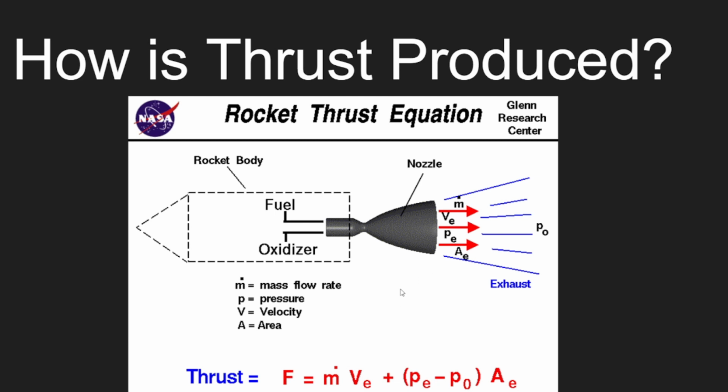So the first thing we clearly notice is that this VE is referring to the horizontal component of the velocity. For example, if our true velocity is going outward at this angle as depicted in the image by these blue lines, we can see that the effective horizontal velocity that will contribute to the mass flow rate force will be only the cosine of this angle.